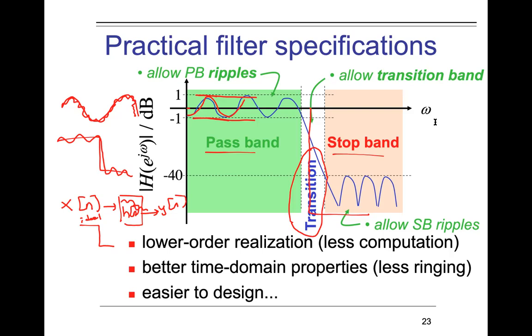Süleyman said noisy output. Arkadaşlar, what did I say? In ideal filters, the impulse response is infinite length, which will cause blurring effects and computation time problems. We will change and have a ripple, but we will have a better impulse response in time domain. But in frequency domain, what is the effect? That's my question here.